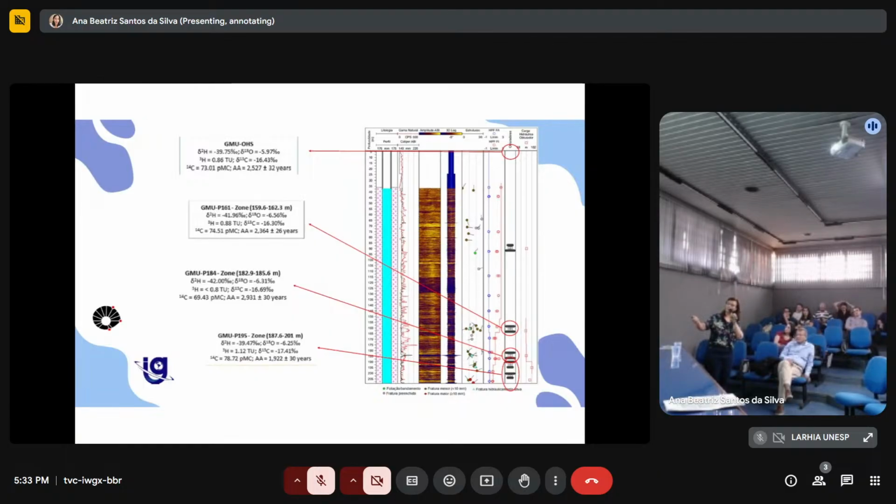And for this part, we found out that there was no water coming into the well. So the only active fractures were really down here in these three intervals. And all this upper part wasn't delivering water to the well at all. And we also collected, but on a different date, an open borehole sample. And this was done with the pump from the well, okay?